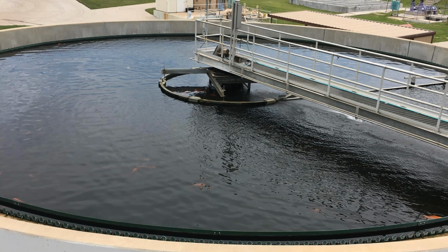So, for example, your clarifiers use gravity and sometimes flocculation to separate solids from liquids. It takes a certain amount of time. The average time that the water is staying in your basin is the detention time. We dial that in by controlling the speed with which effluent enters and exits the clarifier.